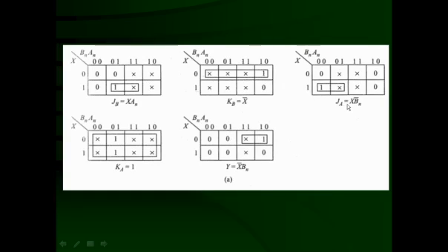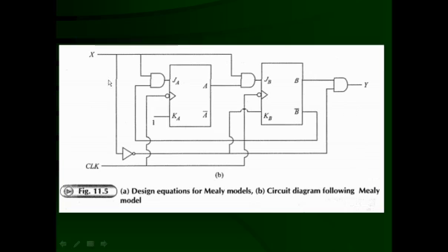J is equal to X Bn bar. So this is Bn bar, taken here as one of the inputs of the AND gate, and this is going to be X. So X Bn bar is the input for this one, and the output is nothing but X Bn bar, that is the J input, and I told you K is required only 1, and the clock is given to both the flip flops simultaneously.